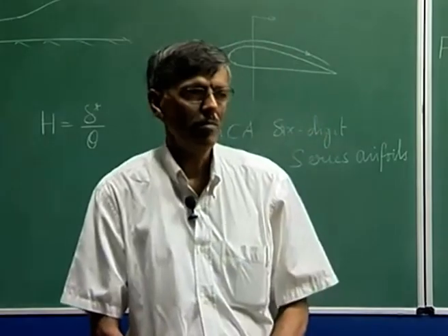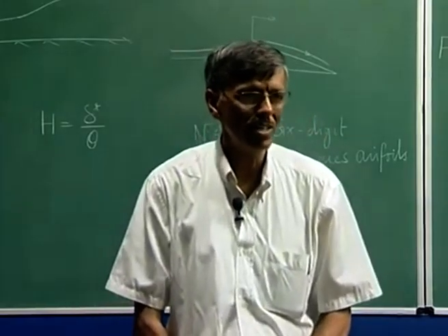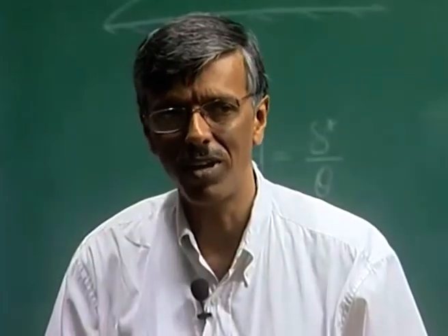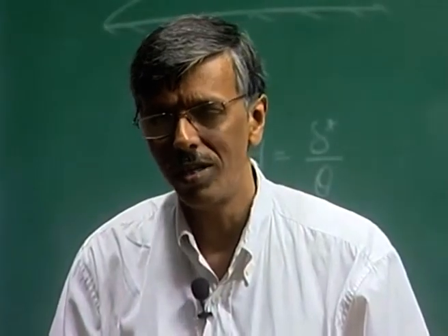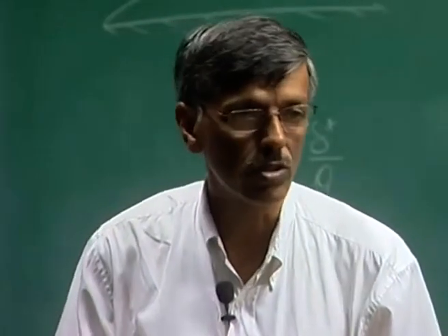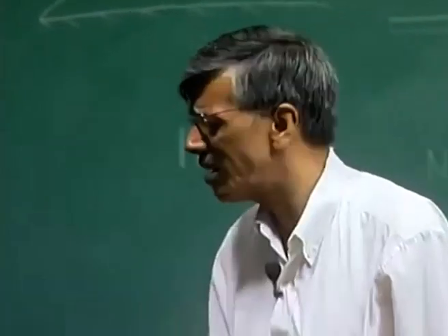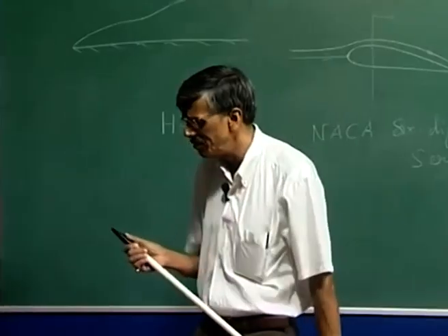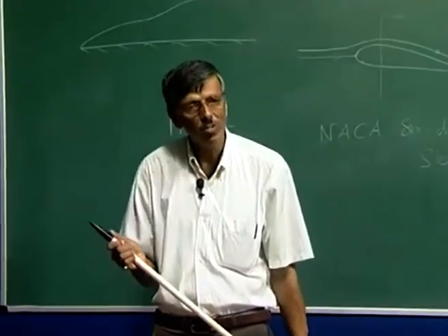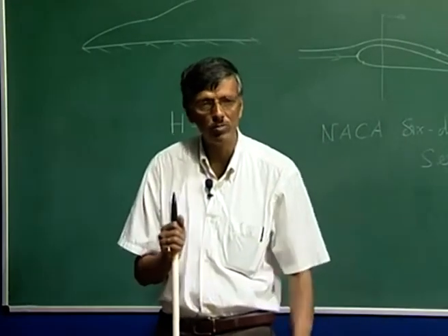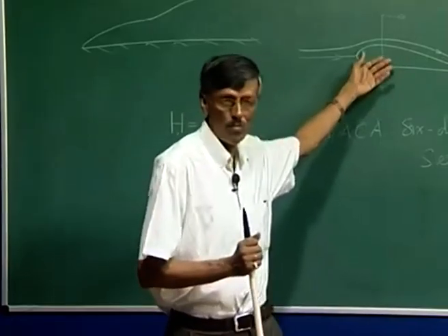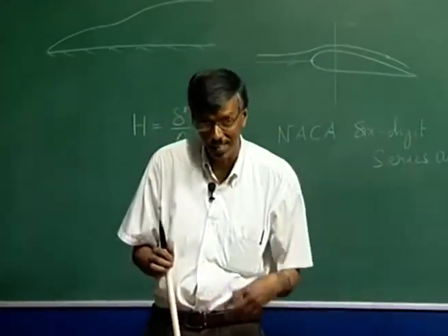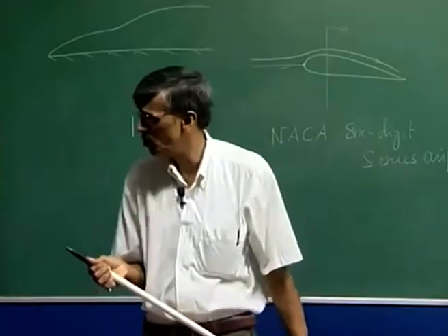However, people have done experiments and they have seen that channel flows can be destabilized at a lower Reynolds number of something like 1000 or so. So, these are the early indications that linear theory is okay for external flow, shear driven flow of a problem of this kind of engineering interest, and it did do a lot of good work.